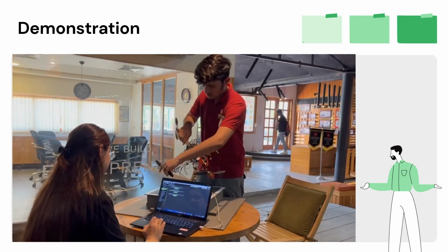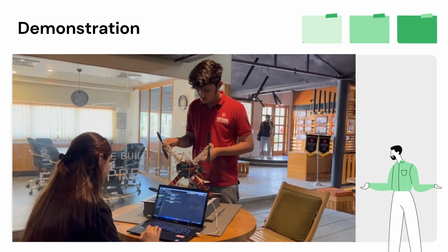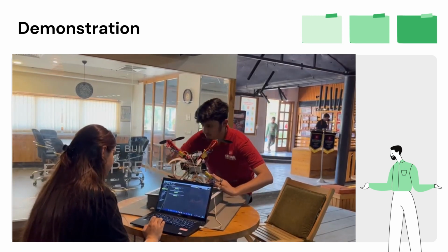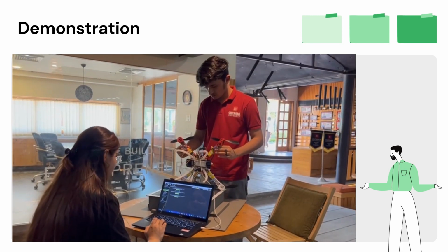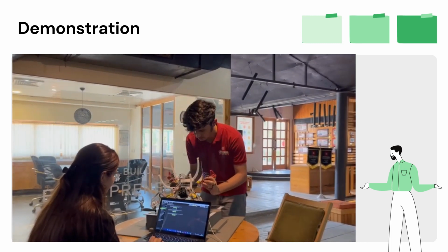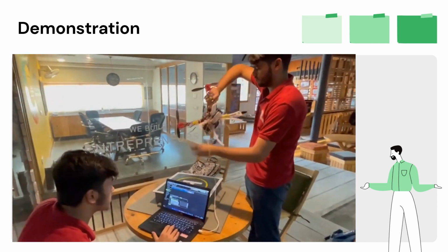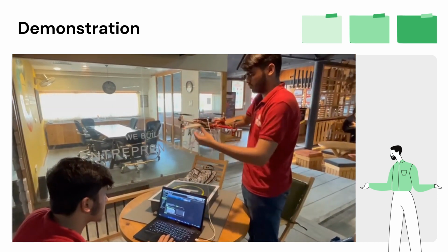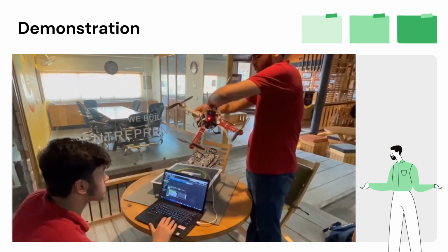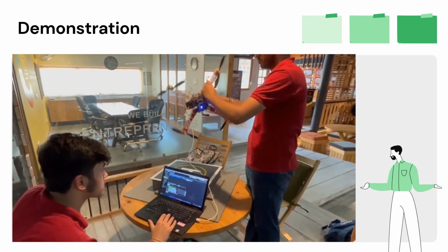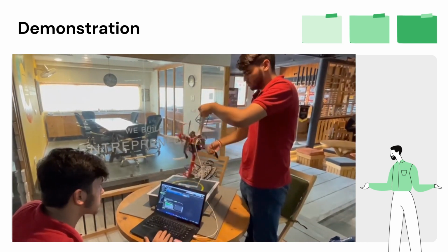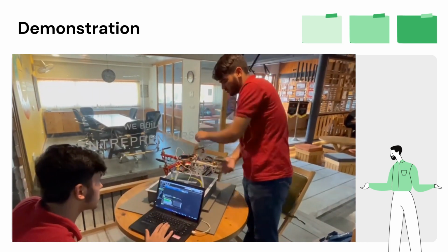So hi guys, in this video, as we can see, Om is calibrating the drone's gyroscope by rotating the drone in all directions, and by doing so he is telling the drone which side is which. And in this video, Karthik is calibrating the drone's gyroscope's 3 axes, that is X, Y, Z. He is doing so by rotating it along all the sides. And as you can see, Om is guiding Karthik using an app called Mission Planner.